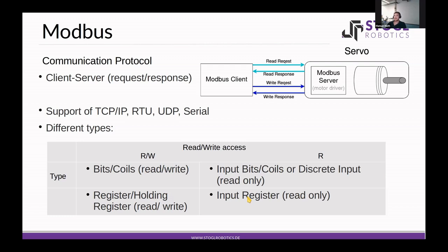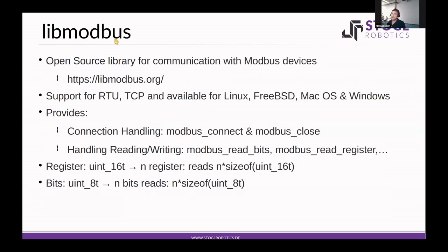And further, there's something called libmodbus, which is an open source library for communication with Modbus devices written in C. Our hardware interface we created relies heavily on this. libmodbus supports RTU and TCP. I focus on TCP here, and it's available for most common operating systems.